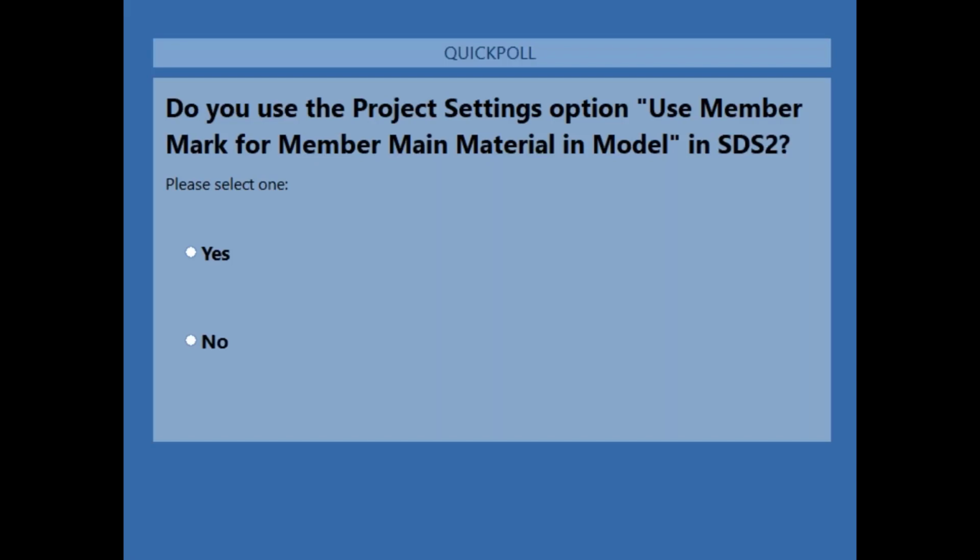Someone said, did I hear correctly, the automatic scheduled IFC export to Trimble? Yeah, you did mention that. Yep, we're basically working on that. I can't give you a date or time, but it'll automatically allow you to schedule to create the folder, and then you can set up your Trimble Connect so that you can just go ahead and pull that every night, because everybody wants that model to be updated.